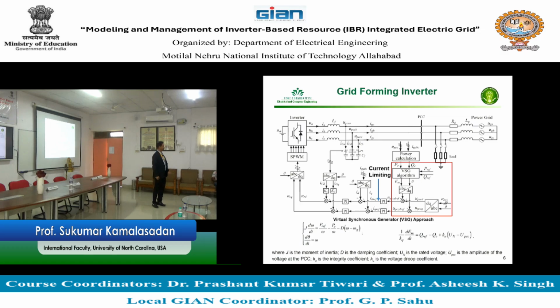For that active power source, there are two ways, like a PV farm or the battery. An active power source from the PV farm also works, but it has to be dispatchable. Remember, we are emulating a synchronous generator. So as long as you have a source that is dispatchable or close to dispatchable, in the inverter world, the only way you can make a dispatchable source is by connecting energy storage or some other device, right? Just photovoltaics is not. Remember the story about dispatchability.